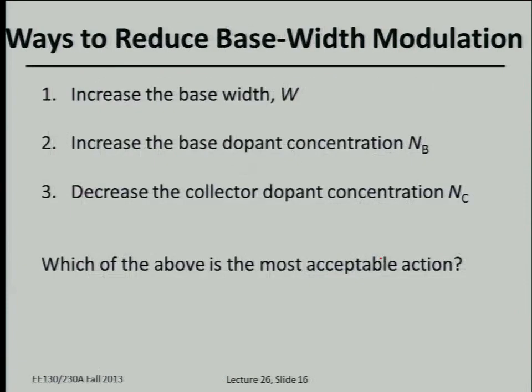All right. So it's actually not desirable. If you want to use a transistor as an amplifier, it reduces the small signal gain, so we like to keep the curve flat. Next week we'll talk about the small signal model again to review why slope is not desirable.